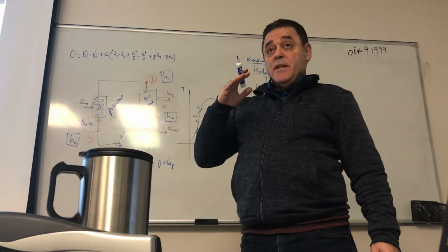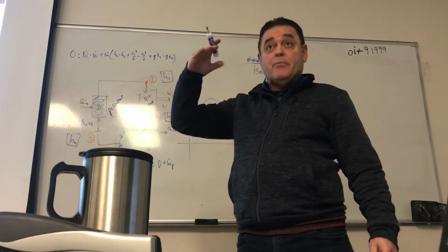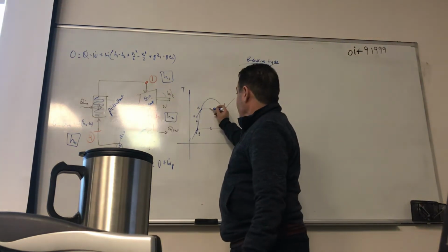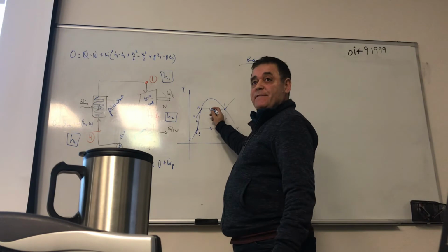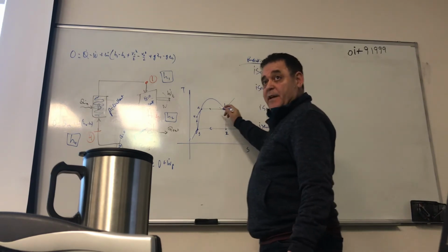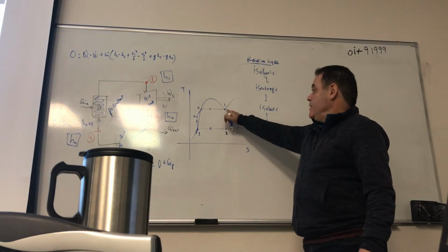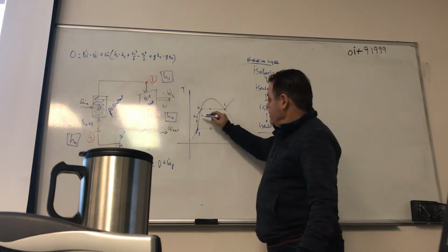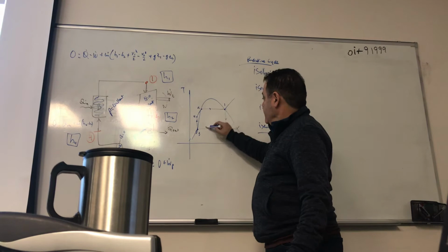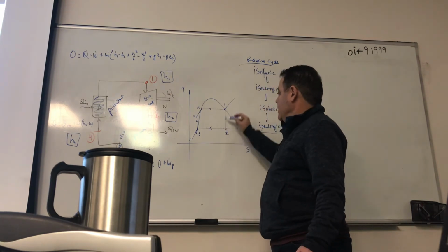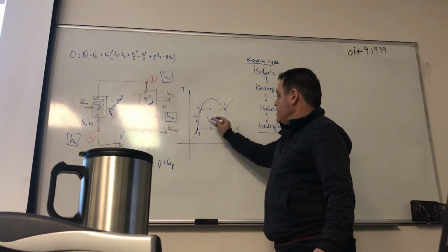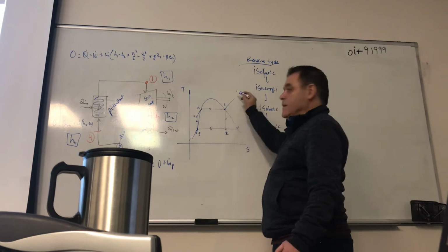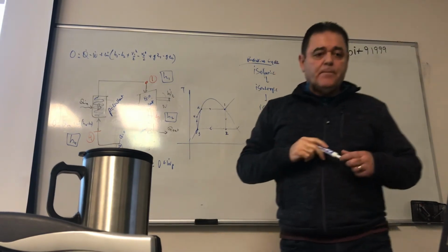Now I continue at that same pressure, right? Now what's happening is a phase change that's occurring until all the water becomes vapor and we're done, okay? That's what the ideal Rankine cycle is all about. 2 isentropic processes and 2 isobaric processes.